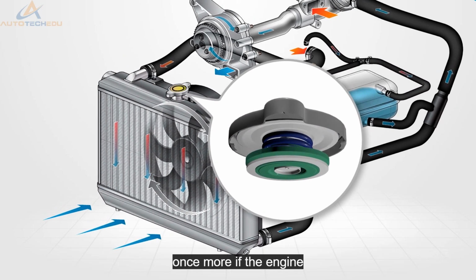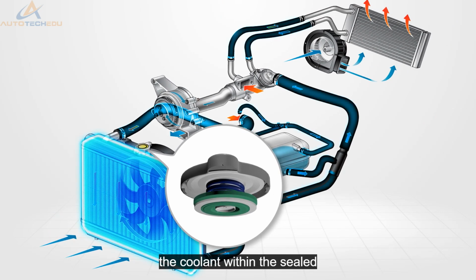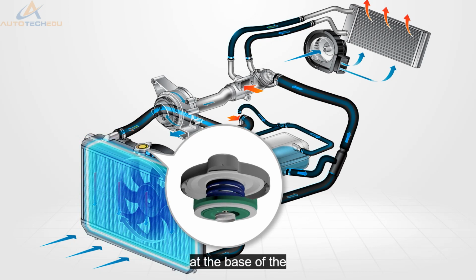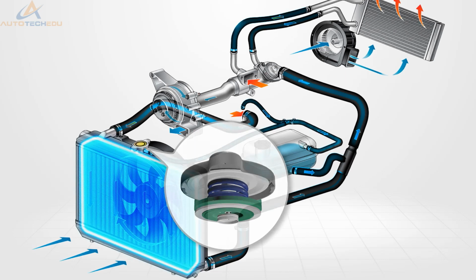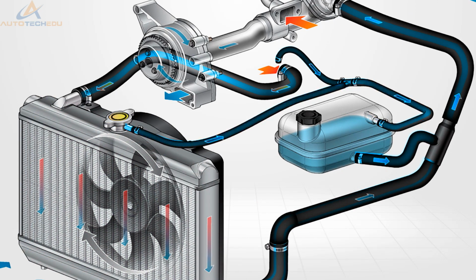If the engine was switched off at this point and allowed to cool, the coolant within the sealed system will contract. This contraction causes a pressure drop at the base of the radiator cap. A vacuum valve built into the cap is pulled from its seat by this low pressure. A pathway opens up to the reservoir and coolant is drawn back into the system until the pressure reaches a balance with atmospheric levels. At this point, the valve will close.